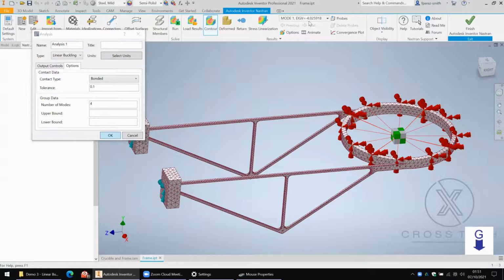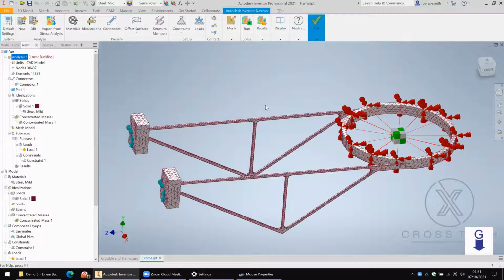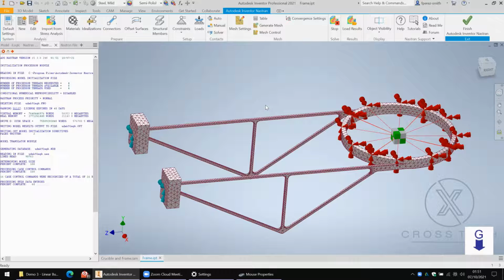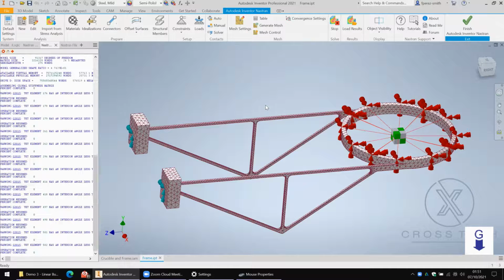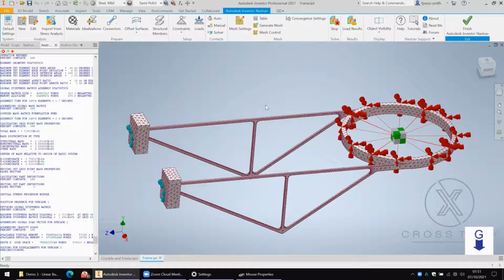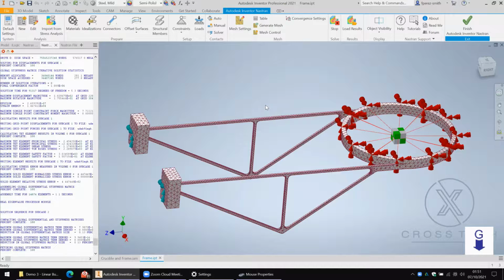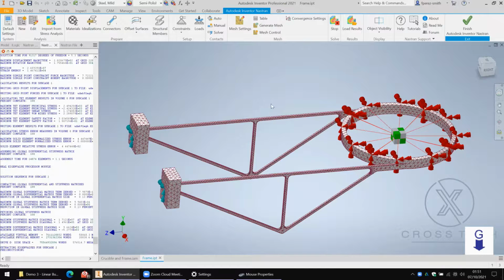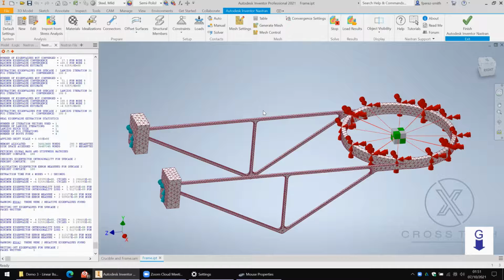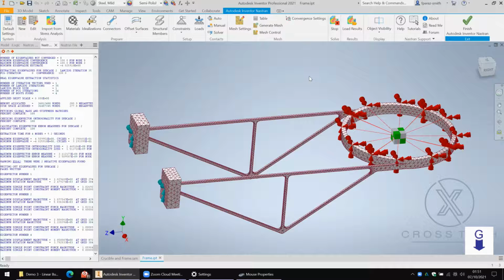So this is actually a good opportunity for learning. If you're confronted with negative values, what you're looking for is the lowest eigenvalue in absolute terms. The lowest absolute eigenvalue is the one that we are interested in for buckling. So say, for example, you got eigenvalues of negative 0.7, 8, 4 and 6. The one that you care about is the 0.7.